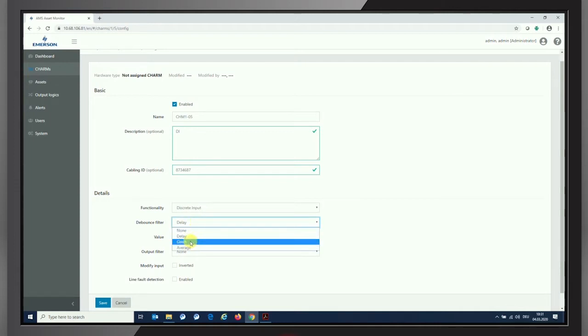Another opportunity is the glitch filter, and the glitch filter means that it is looking after pulses as they are coming in, but whenever a pulse comes in, also for small pulses that may have just 1 millisecond or 2 millisecond width, it will always respond to internal processing with a pulse of 10 milliseconds according to the value that has been set up. So it will transform a small pulse of just a millisecond or two into a pulse of 10 milliseconds internally for further processing.